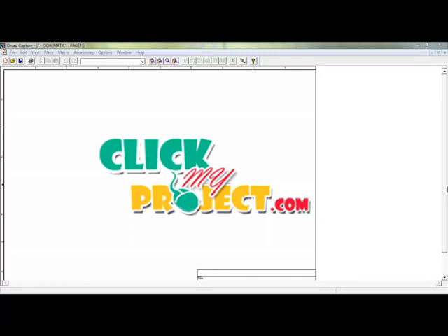Now we simulate this by clicking the setup simulation and selecting the transient or Fourier analysis to choose the timing limitations of our output waveform. Here I choose 100 nanoseconds and 10 nanoseconds for step size. Then click the run option to provide the running operation and extract the waveform structure of our proposed work.